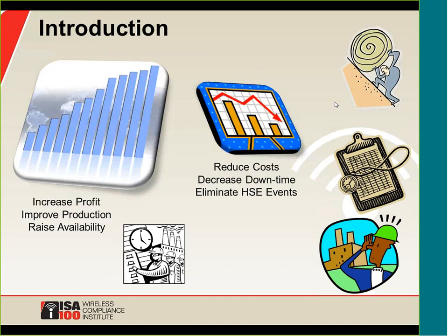Condition monitoring is a primary enabler of increasing safety, increasing machinery availability, and increasing the top line, while simultaneously reducing environmental events, downtime, and operating expenses. Wireless is a key element of economical condition monitoring for the right class of machinery. ISA 100 protocol and standard is a foundational facilitator of getting that wireless data to the right systems and, more importantly, to the right individuals.